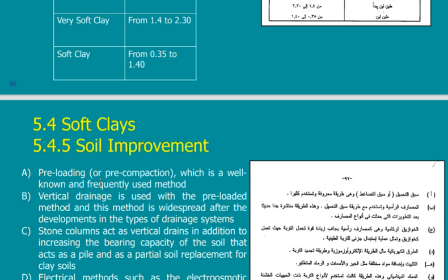So if I manage to collect the water from inside the site and not wait for the water to leave the site, then I will make this operation faster. Because when you put a load on top of your soil, this is your site, and I put a load on top of it, in this case, I will wait for the water that is below to leave the site and go to neighboring sites.